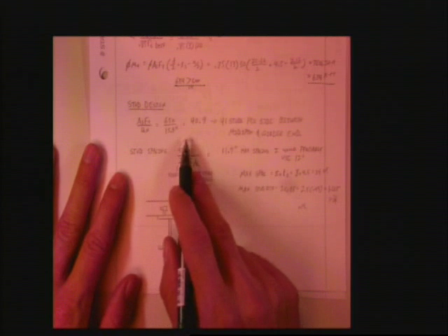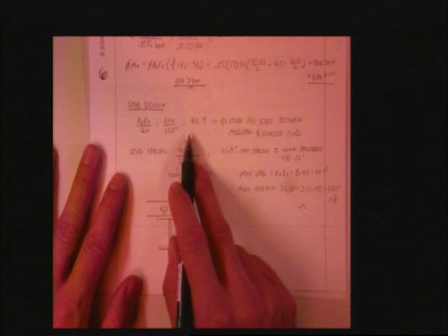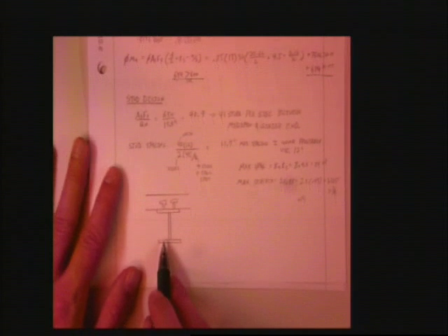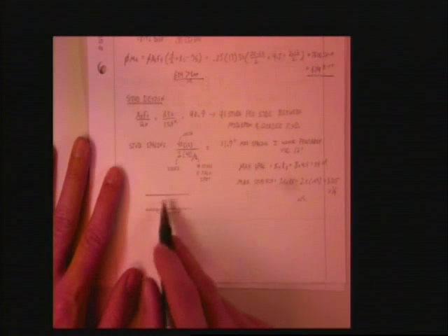Well, it's kind of interesting. We actually need fewer studs in this case, which is kind of interesting. It's because we're not really designing for what we need. We're designing for a stiffness. So as the girder gets smaller, it can't put as much load on the deck.